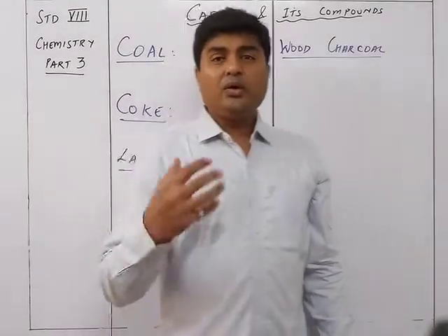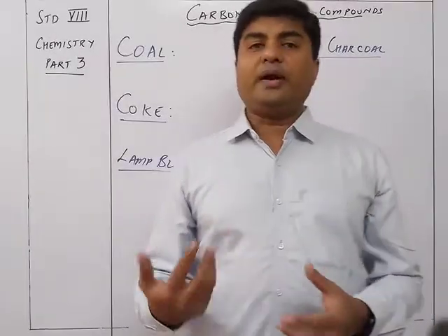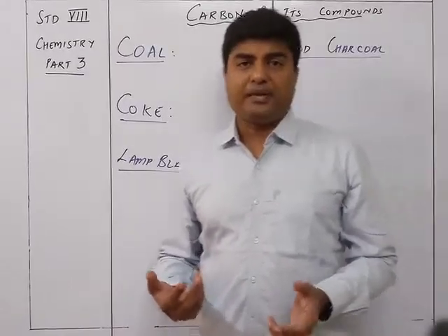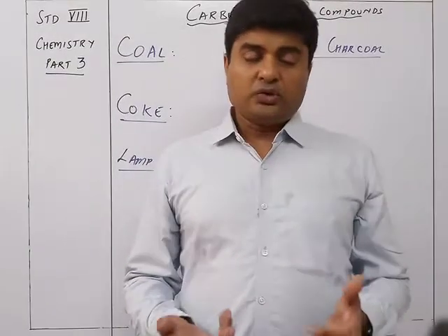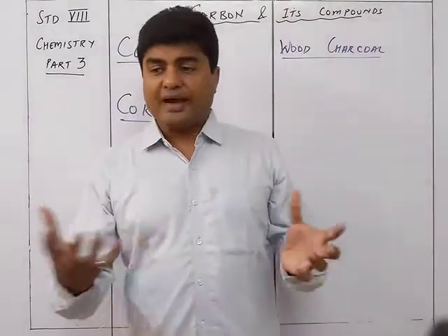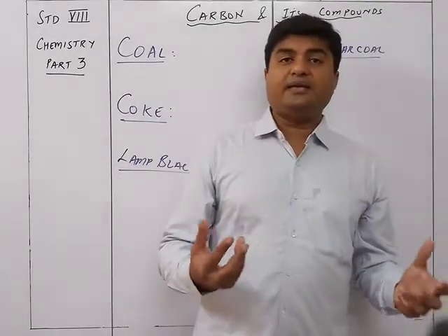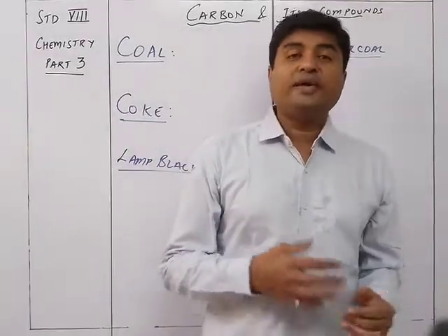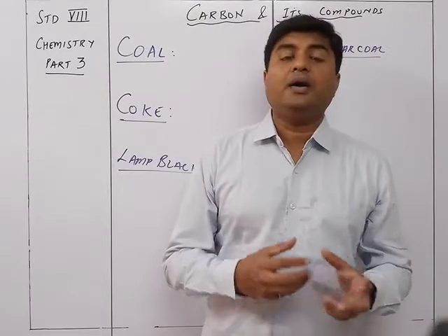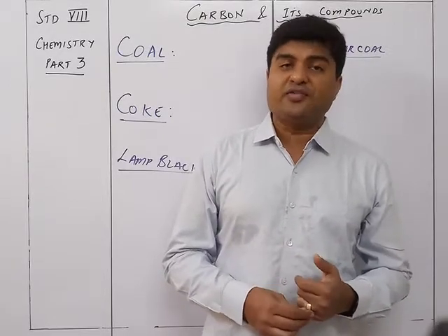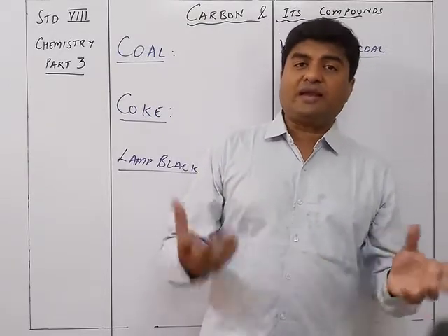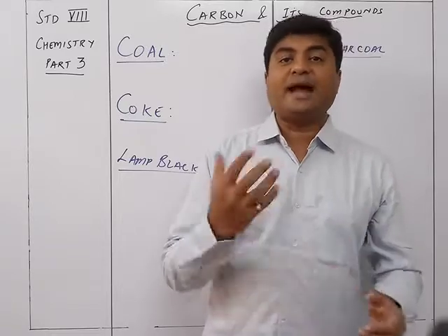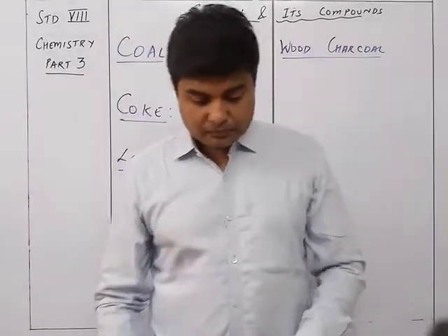So you want more and more of such a thing to happen, that the adsorption should be higher. Adsorption should be higher means more amount of gases should be around it, so that it is helping the process. So for such a condition, we are doing a process which is called activation. That particular product is called the activated wood charcoal.